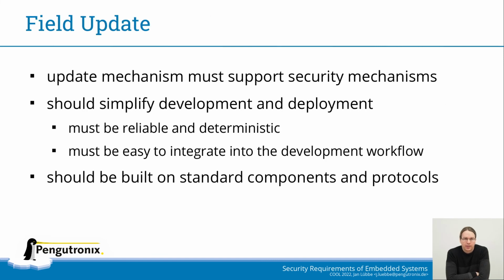So when looking at field updates from a security perspective, we have some requirements regarding the update mechanism. Obviously, it needs to support the security mechanisms and not interfere with them. Things like a verified boot, where you have assigned software that needs to be bit identical, that needs to be supported by the update mechanism. And it should also be as simple as possible to handle deployment and development.